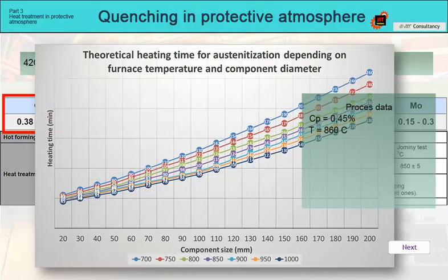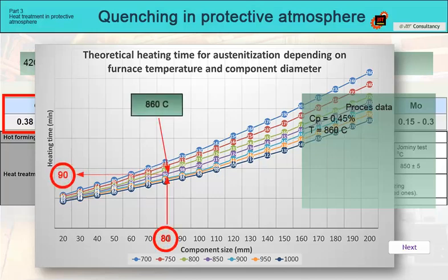With regard to the composition of the batch, then, with a coefficient of 2, a total of 180 minutes. We will also add the time for austenitization of 30 minutes, and we have the resulting time from loading the batch into the furnace to opening the unloading door and subsequent quenching of 210 minutes.